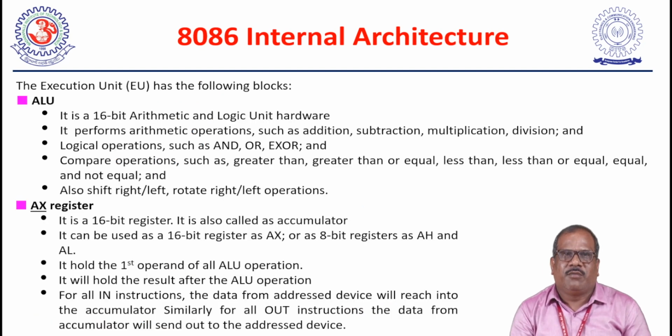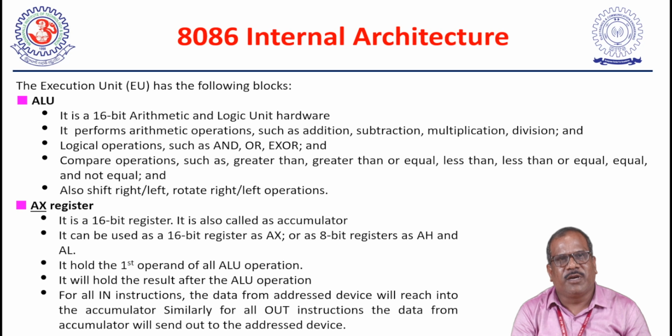So the BIU principle is now completed. We go on to the various block operations of the execution unit. The execution unit has a 16-bit ALU. This 16-bit arithmetic logical unit can perform 16-bit arithmetic as well as logical functions.